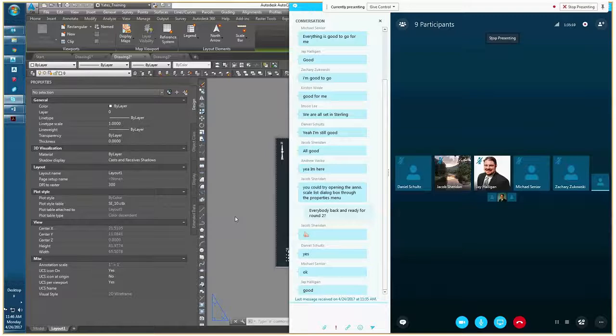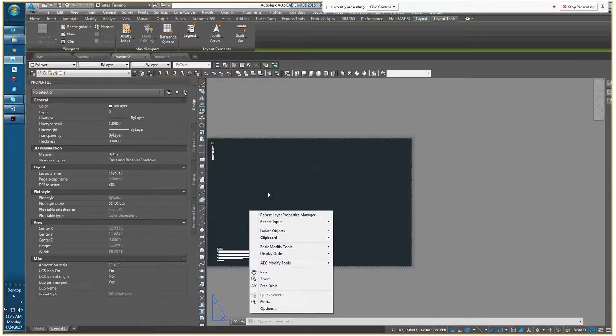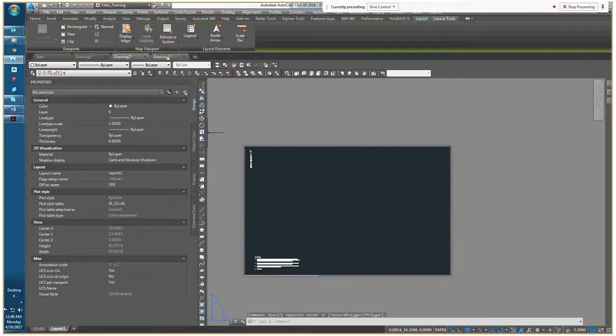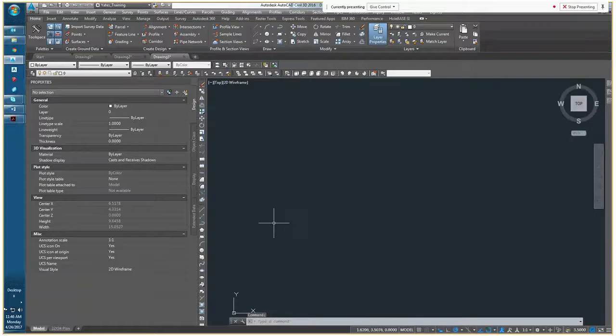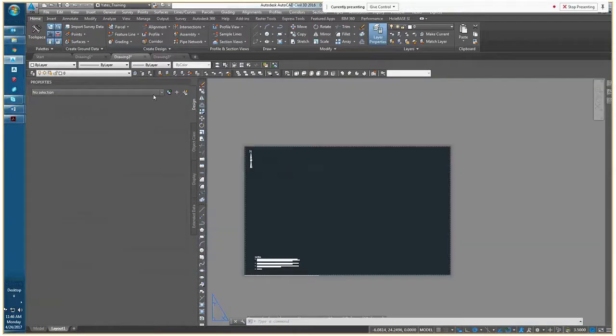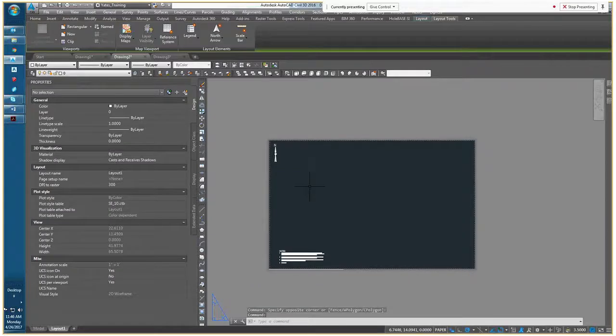There's also a trick if, for instance, you're working in a detailed DWG template and you suddenly realize that you're going to need surfaces, alignments, or other things that are style-based. There is a trick to be able to get those styles into that detailed DWG template, and it's pretty easy to do. And I often will keep a copy of this on my desktop.